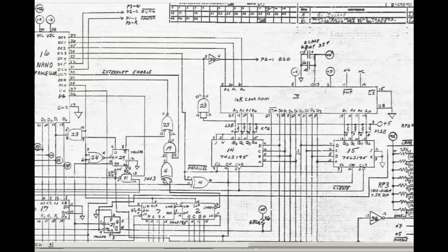So one circuit I want to explain fairly briefly, but it's quite a clever circuit, and it's one that we do really need to simulate in the software, so I thought I would briefly explain how this works, because on first sight it can look a bit unusual. So this is the data to serial stream converter. All the data going to the print head goes out of this pin, so it goes out as a serial data stream, but it comes out of these shift registers.